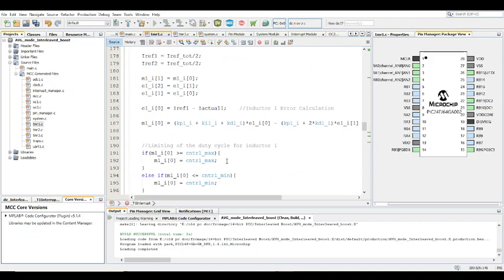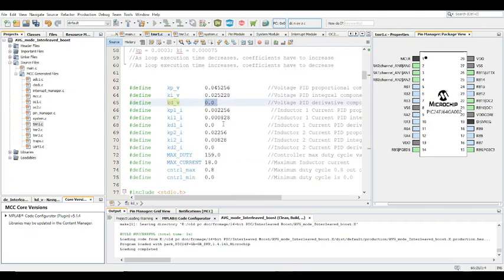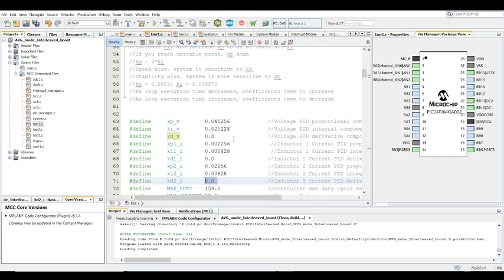And really, I keep saying PID control, but this is really a PI controller routine, because if you look at the coefficients up here, there's nothing for the KD. It's 0.0, because I found that it makes very little difference when I change the KD. There is a benefit to adding a KD, but you have to know exactly what kind of KD you want to use. These particular coefficients are thumb-sucked. Not pulled out of thin air, but holistically, there are some assumed values there, and some trial and error going on. So you don't want to add a derivative constant using trial and error. You want to really calculate and make sure it's precise before you add a KD value.